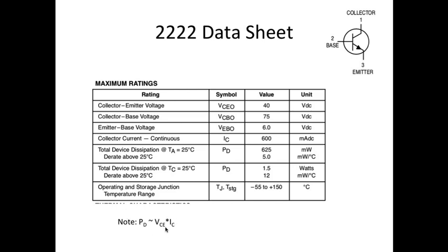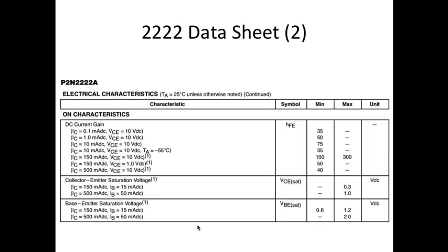Notice that the power dissipation we usually approximate as VCE times IC. So anytime I ask you to approximate power for a BJT, you can use this equation. There's also a VBE term in there, but it's negligible because it's VBE times IB, and IB is 100 times or so less than IC, so you just throw that one away. The other thing to remember is that you can ask CircuitLab to compute P directly. I'll say more about that in a minute.